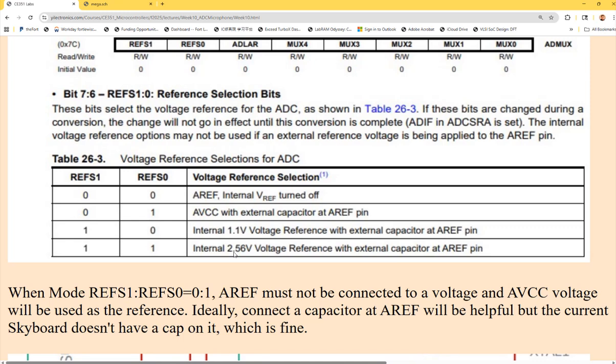So there will be a sensor, and here's the ADC. What's in the middle? What's in the middle? A black box, right? So make it happen, please. What's in the middle? Amplifiers, right? You want to amplify it to the range.